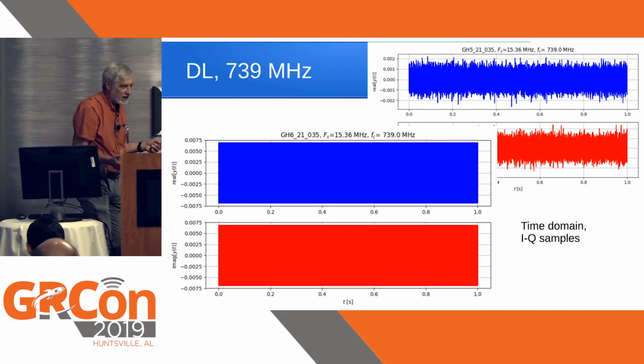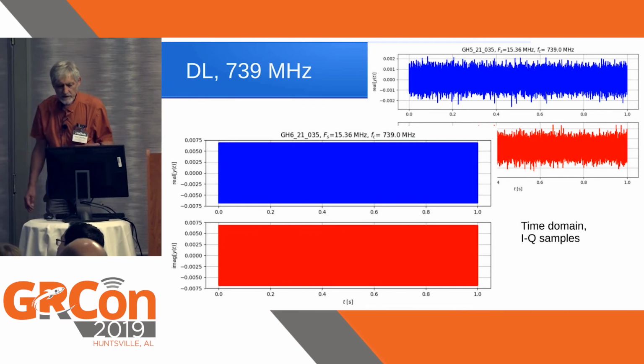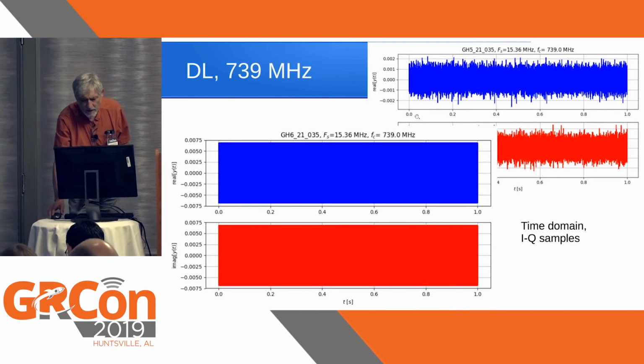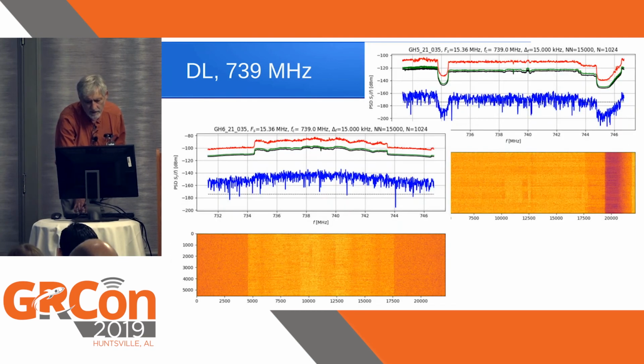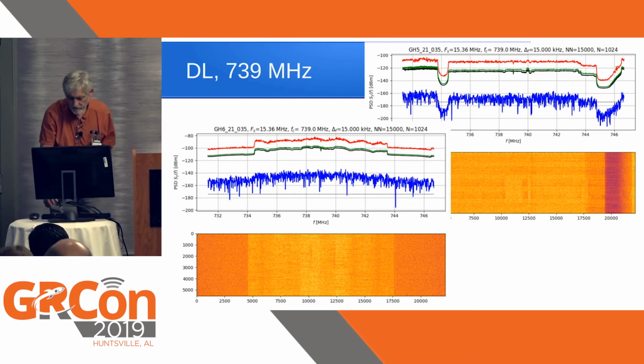Okay, the sensor actually happens to be in close proximity with either the AT&T or Verizon downlink, and so it's just overdriving the whole thing, whereas the sensor that was far enough away has a time domain signal that looks like this. Okay, and so what does that mean? It means that the input of the sensor is actually, in this particular case, blocked or desensitized by that strong signal that is out of band.